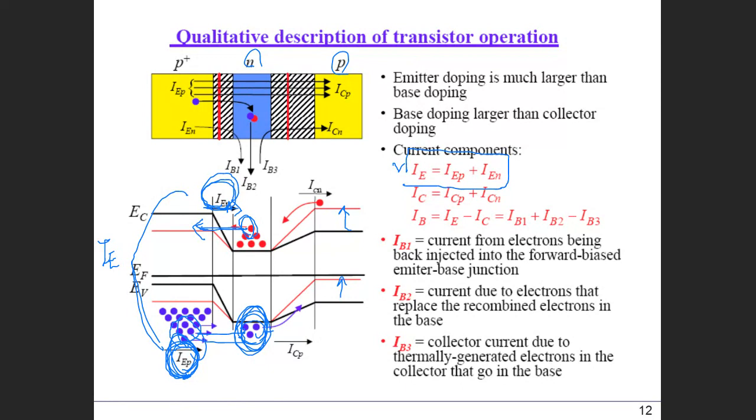And then when the hole migrates close to this electric field region between the base and collector, this hole is swept by the electric field. Because the hole is a positive charge, and the electric field points this way, once the holes go into the depletion region, due to the negative potential in the collector side, you are going to see the holes swept to this collector side.